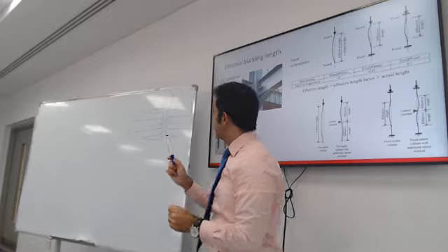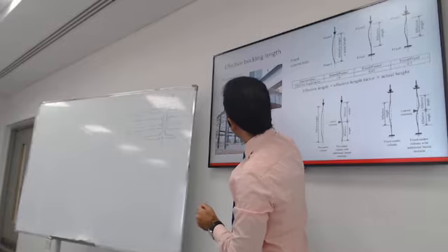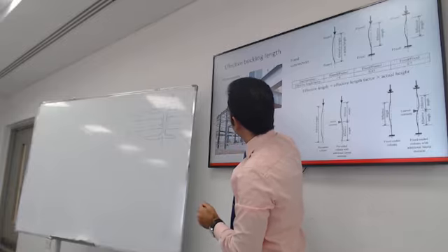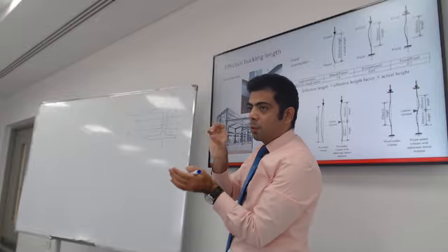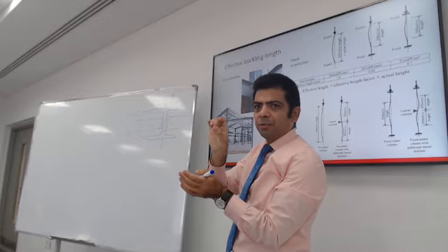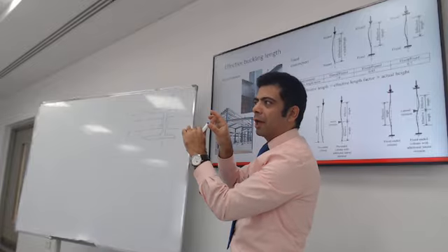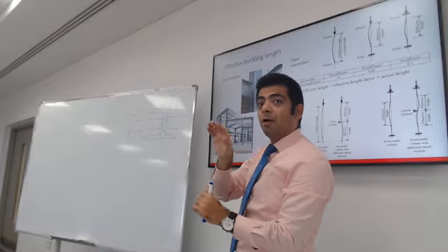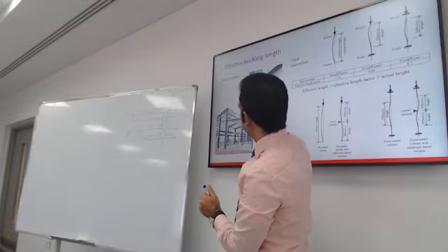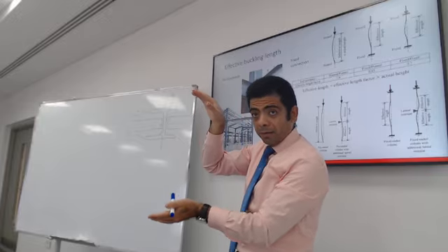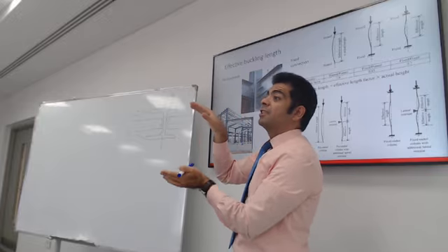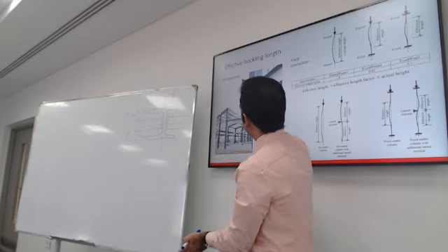If you look at the connection to the left, you'll clearly see a gap between the flanges of the beam and the column. So it's supported like at the center line of the beam. This typical connection will allow some rotation. On the opposite side, the bolts are on the top flange and the bottom flange, and the bottom flange is actually stiffened. It's actually deeper than the beam.